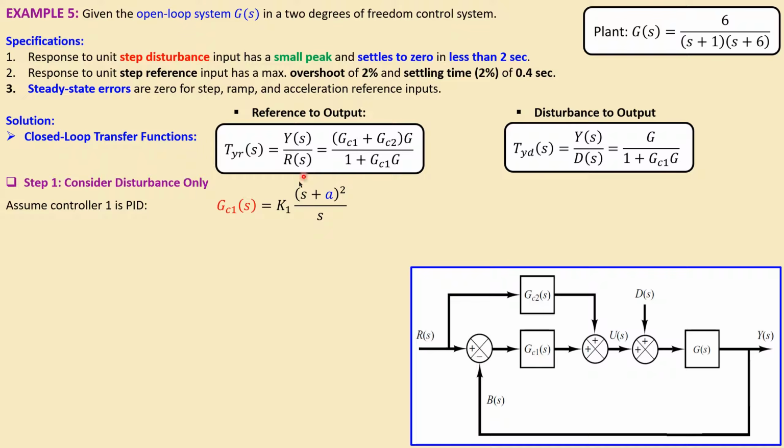In this case, it is chosen to be at the same location, so we have a double zero, and we have a gain of the PID controller, and we have again the pole at origin. Now, the root locus equation is 1 plus the loop transfer function equal to 0.